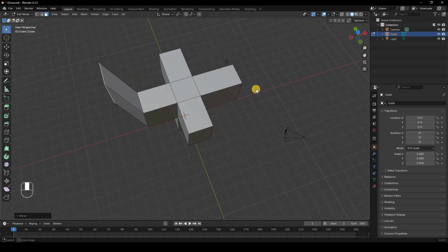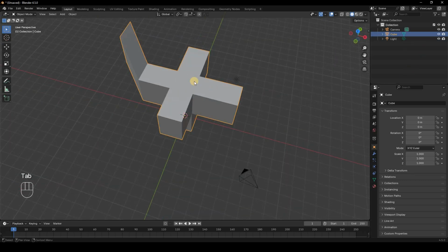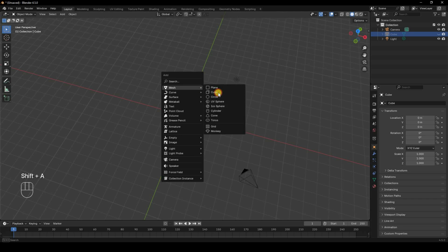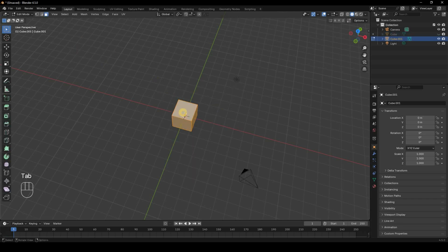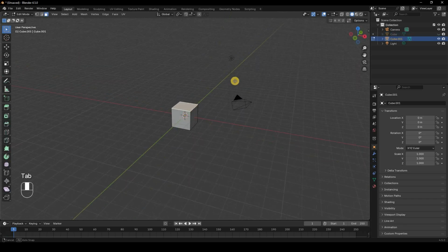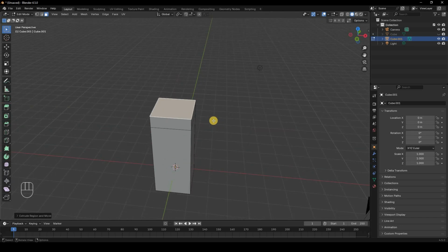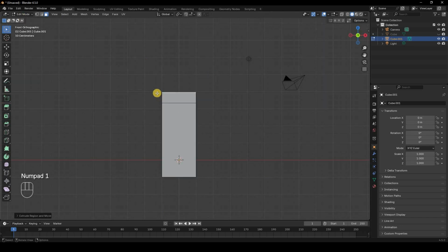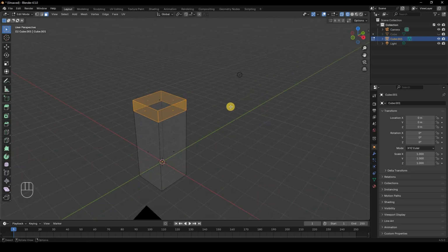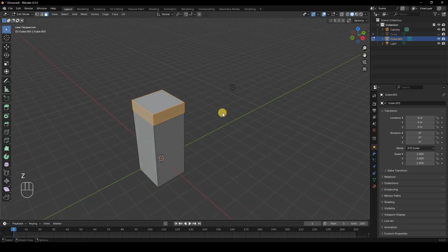Suppose you want to model a chimney. I'll just take this cube, and we can select this face, move it up, and extrude it like this, and just get our basic run-of-the-mill chimney. So the first option, again, I'll just have to show you the other extrusion option. I just want this to be expanded along all of these faces, so I'm going to press Alt E, and now it's going to ask me what I want to do.